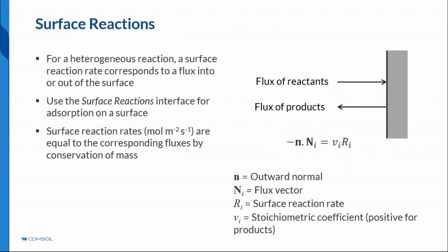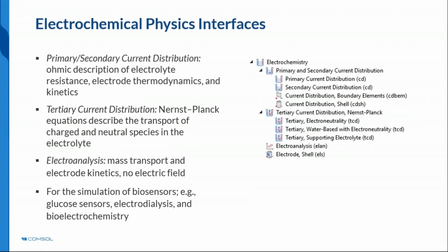Surface reactions are important in biosensors as well as more general heterogeneous reactions such as reactions on catalytic surfaces. Instead of bulk consumption rate across the domain, the rate of reaction is described as a boundary flux, acting as a source or sink of material. At the surface, concentration gradients will develop to match the flux demand from the reaction. In mass transfer limited systems, significant concentration gradients may occur, and the transport of species will become limiting, reducing the observed reaction rate.